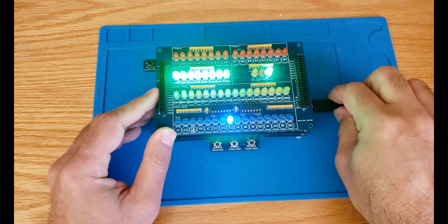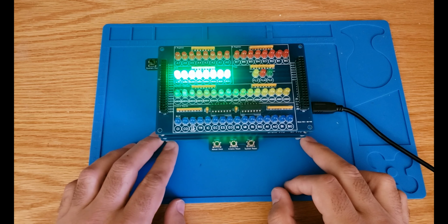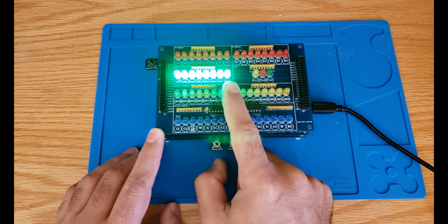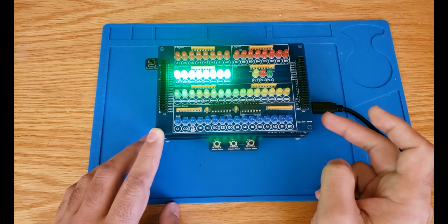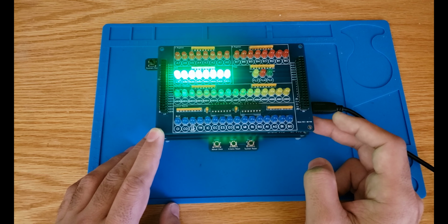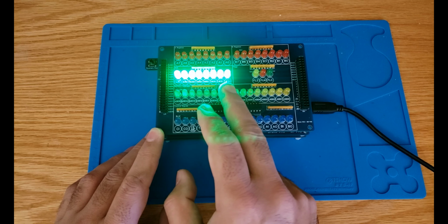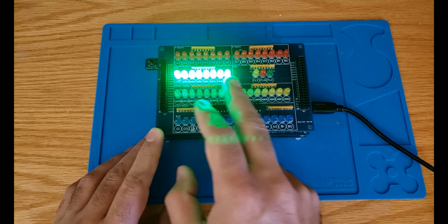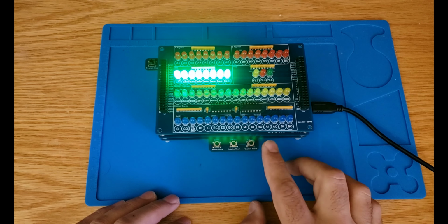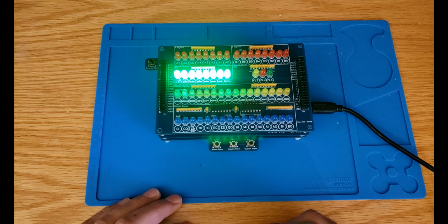All right, so let's connect the power. I connected the power, and the first thing that you probably have noticed is that all our bus lines are set to high. It is normal because, if you remember, when we were building the clock circuit, I explained that we have a resistor array there that is tying all of our bus lines to high. So essentially, when you're not writing to the bus lines, all of them are set to high, and that's why those LEDs are already on. Now, we don't have any sketch loaded on the Arduino Mega right now, so we're going to have a look at the sketch and load it and see what will happen.